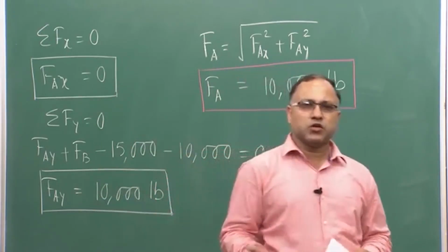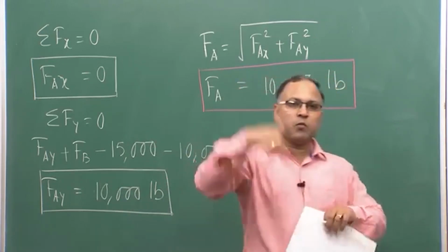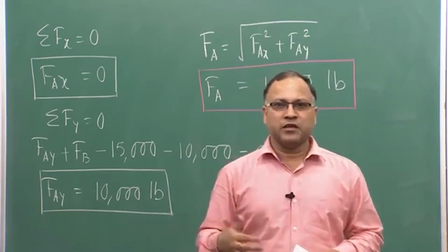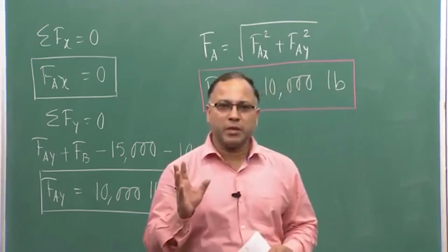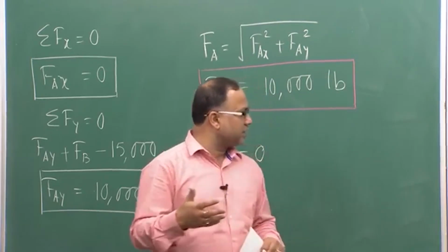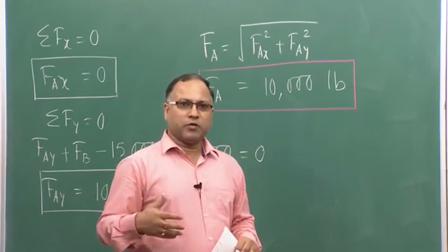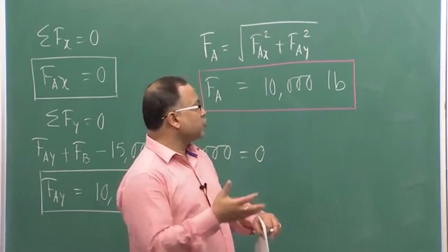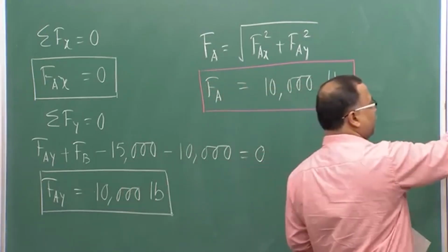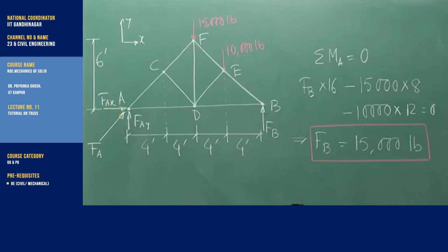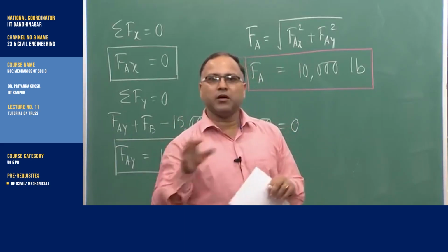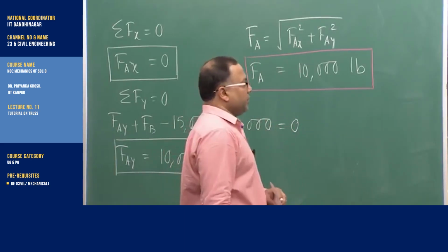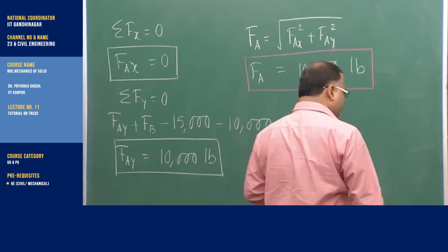Similarly, vice versa is also true, that if you do not have the force in the y direction, that is the vertical direction, there will be no vertical reaction. So, that is the thing you should remember, and we will do this later on, because most of the times we will not be showing all the reactive forces, horizontal as well as vertical. By seeing simply the loading condition, we will choose our reactions.